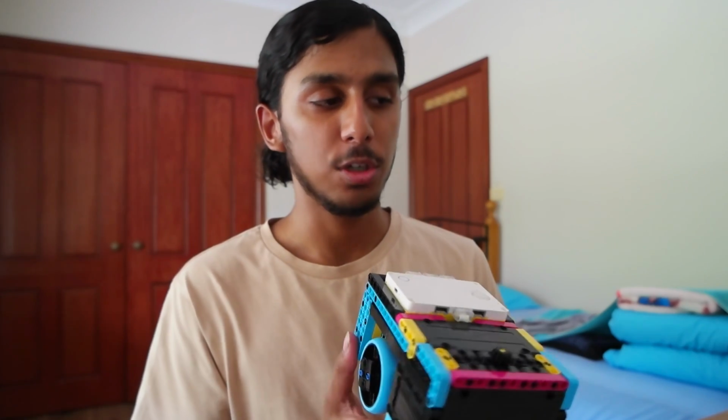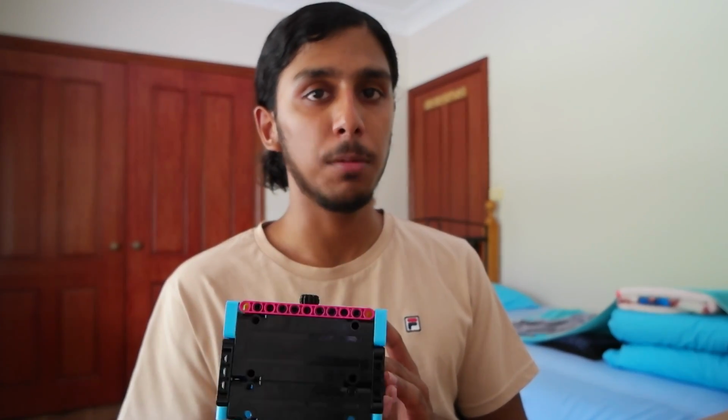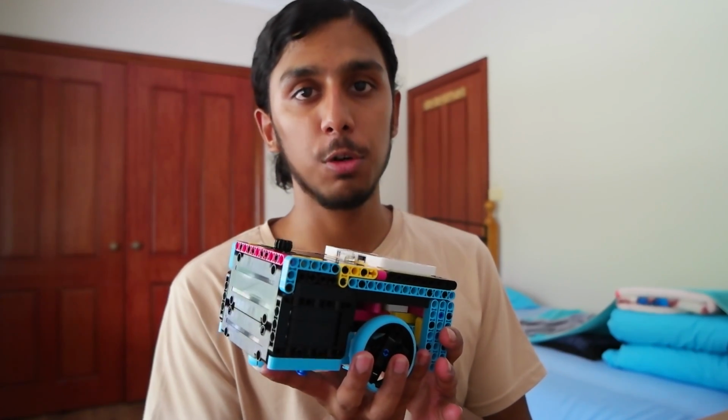The gyro straight is what we call a function, because it will go straight. If you want to go straight again, copy paste the same command, it'll go straight again. In the future, we'll learn how to turn accurately. So turning is probably one of the biggest inaccuracies a robot can have, especially on an FLL map. Because you can imagine a 2-degree error of a turn can really add up over time, and it can end up in a different position. So you can also learn a line follower and a line scoring program.